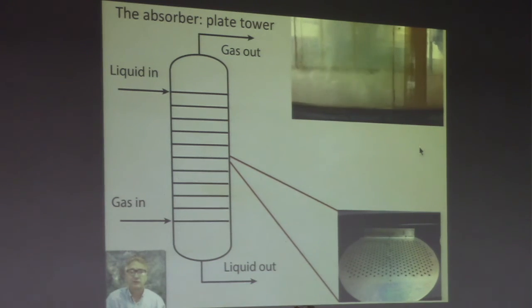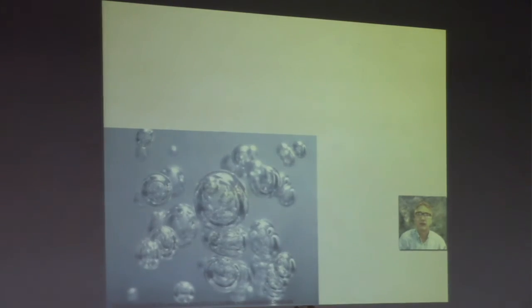In order to understand the effects of mass transfer, I first need to look very, very carefully at the interface between the vapor and liquid phase. In this cartoon I've taken from Wikipedia, I show a bubble in a fluid. And in particular, I want to understand the concentration of CO2 inside the bubble as it goes across the interface of the bubble and into the bulk liquid. So here's a graph in which I imagine that.